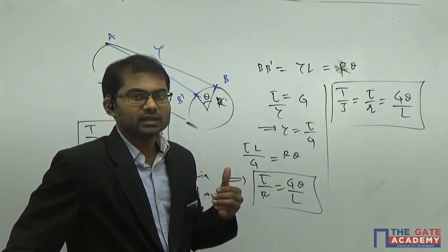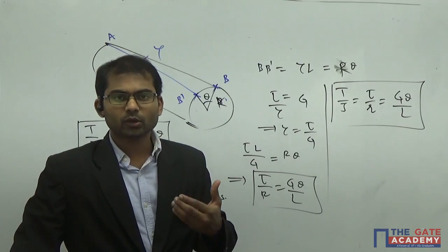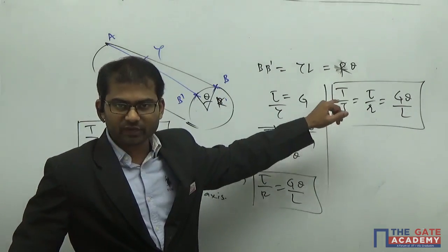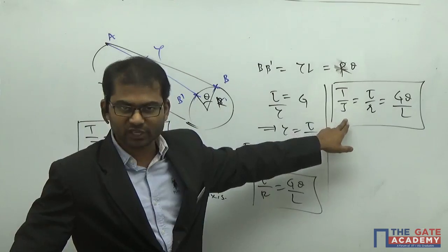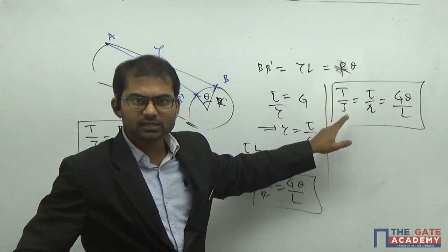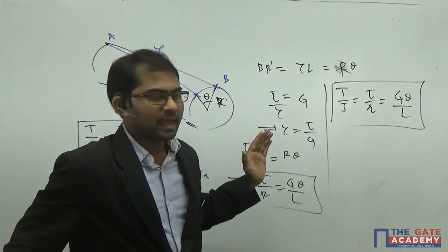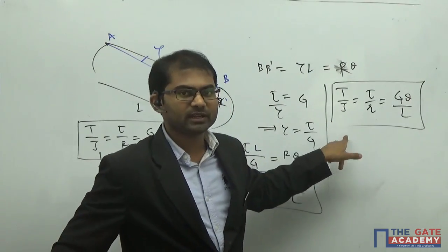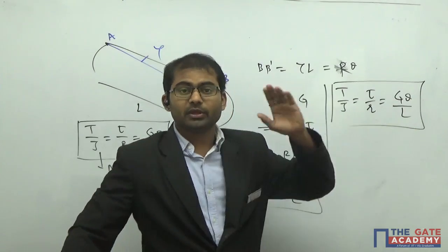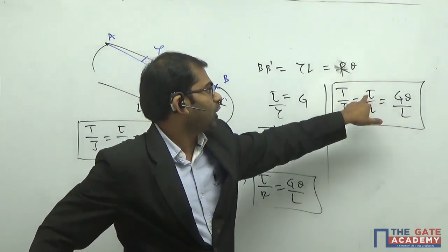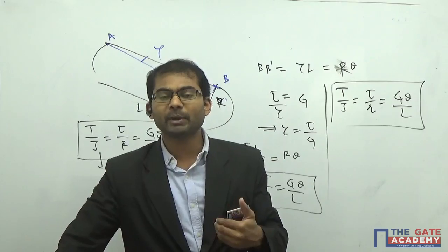So the meaning is, if I create a torque T on a member having a polar moment of inertia J, at a distance of r the shear stress is given by tau. In other way, for a length of L, the angular twist produced because of the torque applied T is given by theta. Here you have to understand that the tau values and theta values are dependent parameters.